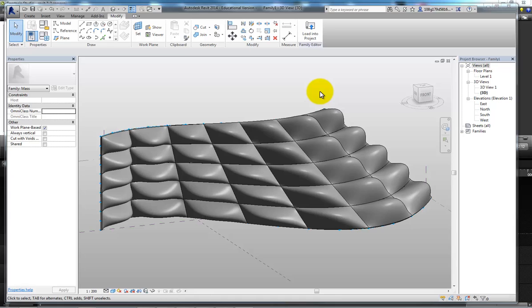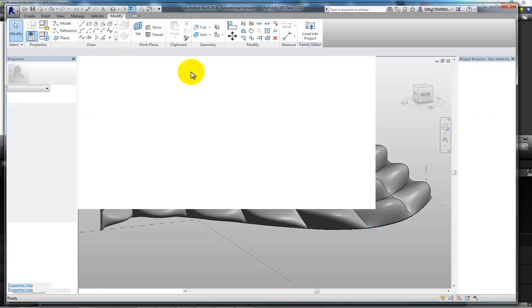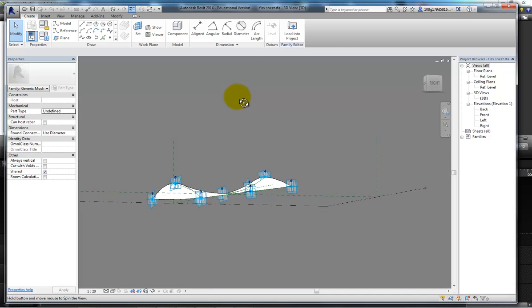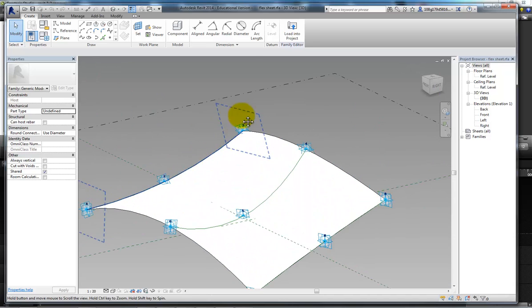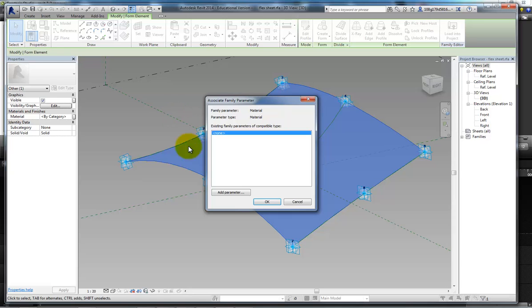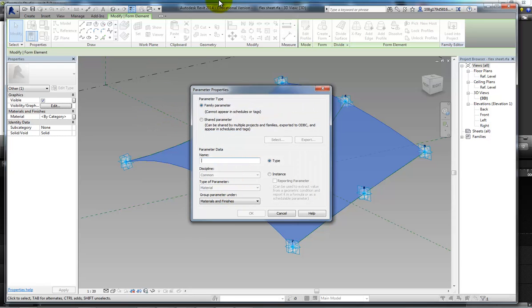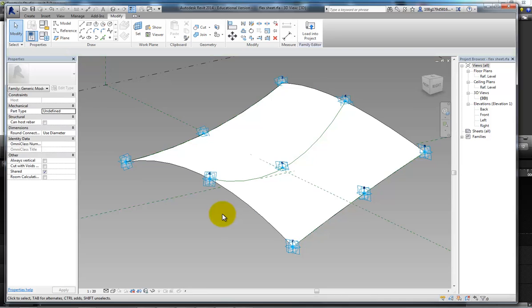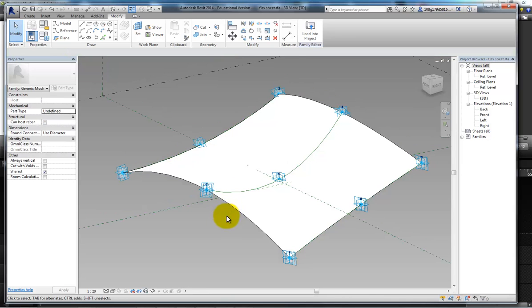To keep it clear and simple, we'll just use the original flexible sheet. So go back, find that. So here's our original flexible sheet. First thing we're going to do, let's add a parameter to this sheet within the material section. Material of the sheet. OK that. Turn that into glass. We'll add a contrasting material to the mullion so we can see the difference.